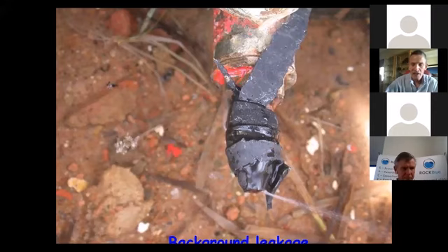Now, it's important to understand every network will leak. You cannot get rid of leakage. You can find burst leakage using normal leak detection methods such as sounding, correlation, etc. You cannot find background leakage because it's so small and the equipment won't pick up the noise from a typical background leak. However, background leakage can often be so significant that it's greater than the burst leakage. So it's important to understand every system will have leaks. Some of them will be burst leaks that you can find with leak detection equipment. Others will be background leaks that you can only repair through replacing the network or through pressure management.